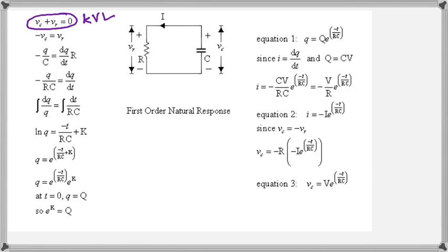So we're starting here with KVL, Kirchhoff's voltage law around that circuit. And that gives us two voltages adding up to zero. So that's what we are doing. And you see the next thing we are doing here is we are using Ohm's law to replace the voltage with an IR statement. V equals IR. So we substitute I and R in place of V, but we know that I is equal to the dq upon dt, so we put that in place of the I.